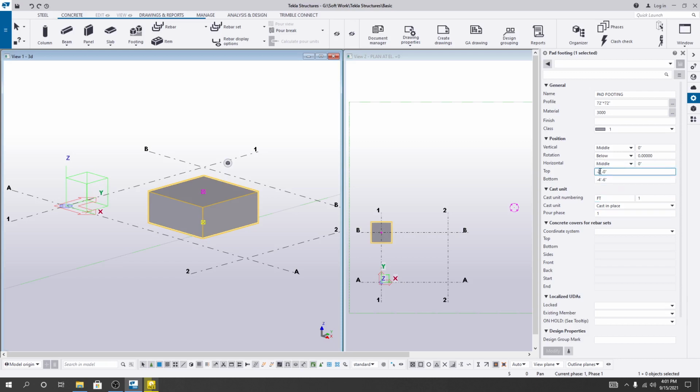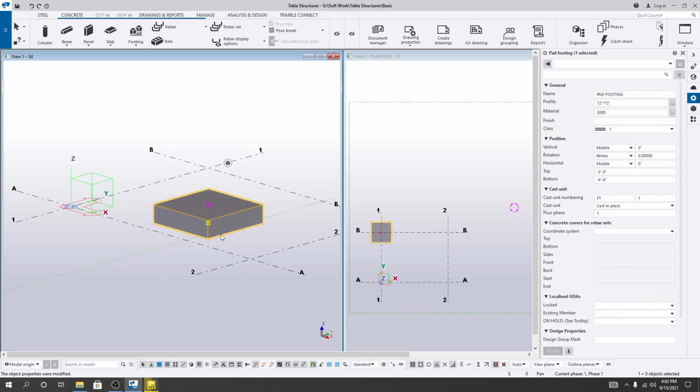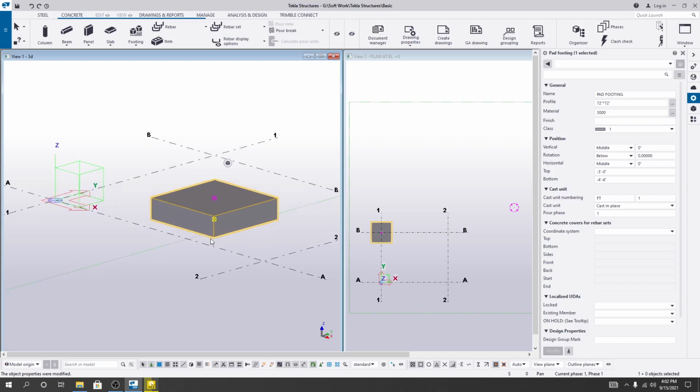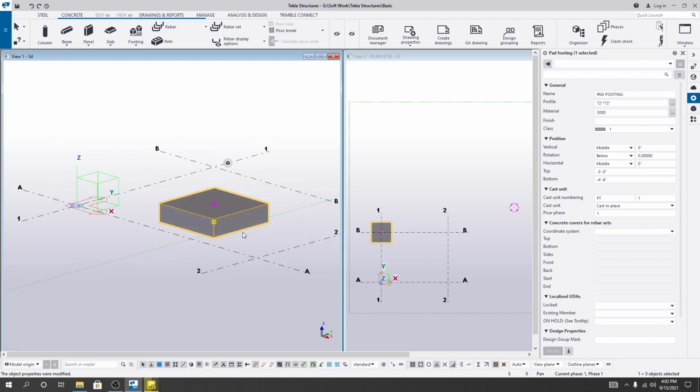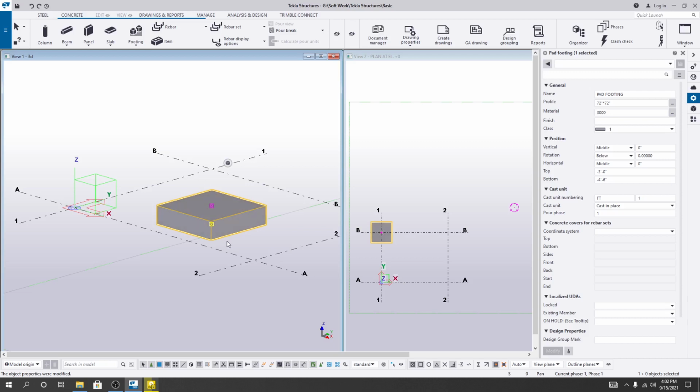And if you just provide here 3 feet below, and if you provide here 5 feet, or if you provide here 4 feet 6 inches, that means it will create an 18 inch depth or 1 foot 6 inch depth foundation. After that, apply. Just see, you can see here this value is available. Clear? Actually, this is the issue, how we can create that foundation.